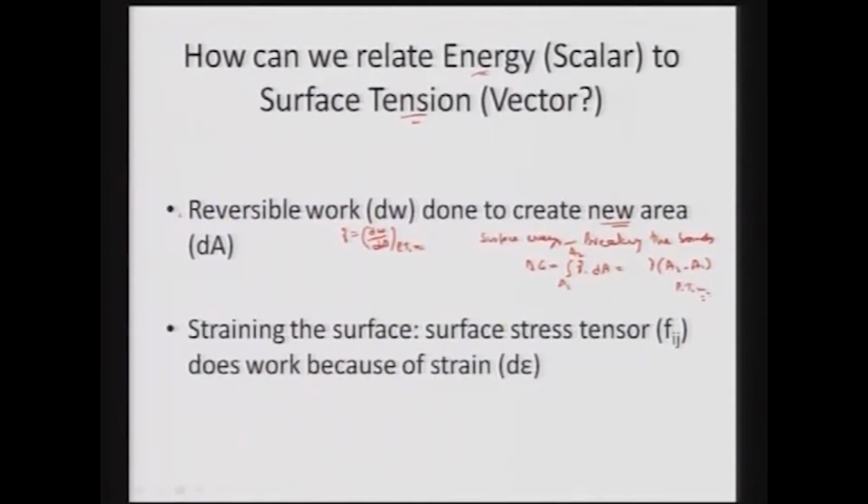Now, the second concept is that gamma, the surface tension, is a function of the orientation of the crystal as well. So in solids, if we have the 111 plane being stretched, or the 110 plane, or the 100 plane, the overall energy or surface tension required for stretching those surfaces will be very, very different.